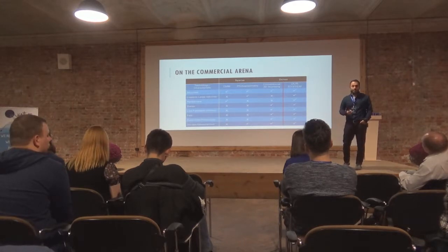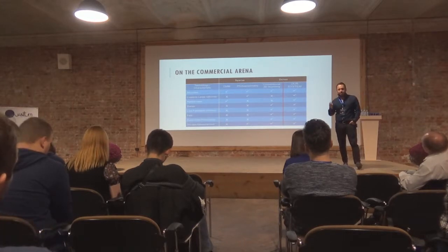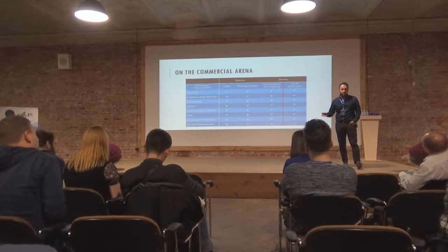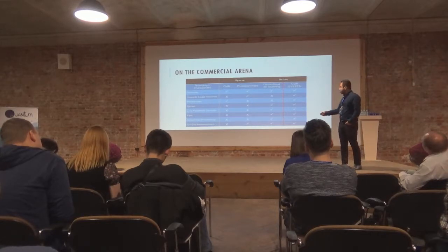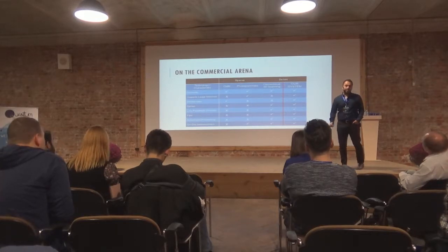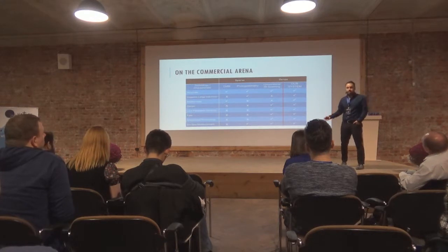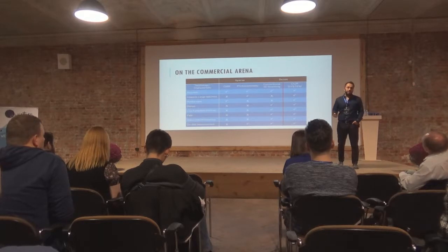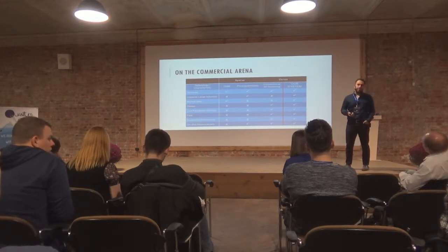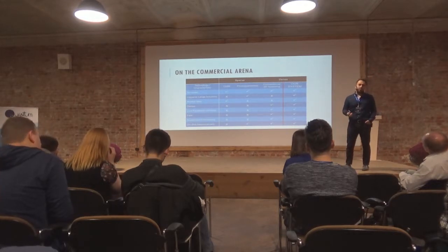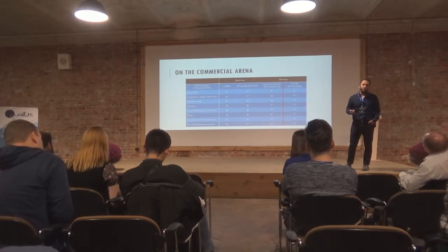Maybe another method. But if you can live with an accuracy of 1 millimeter on this 10 meter large object, then there is no reason to choose a CMM over this. So in that sense it's a CMM replacement. But if you want micrometer accuracy, then it's not a CMM replacement. Also think about it. When CMMs were invented, there was no multiple view geometry and there were no software solutions. Basically, we lacked the algorithms.